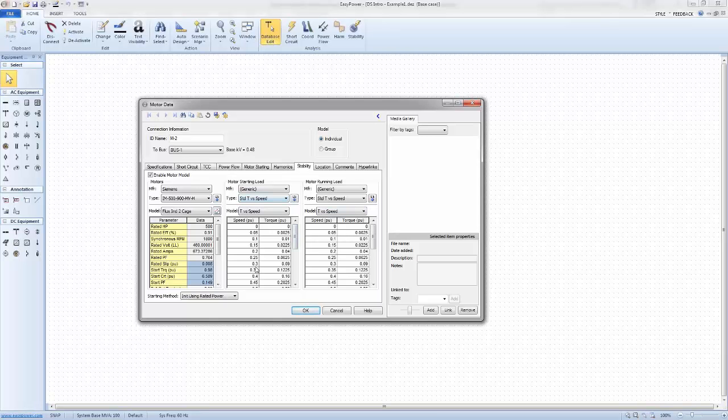And these models and curves are torque versus speed, or torque versus slip. Those of you who have more knowledge about induction machines know that torque versus slip is one of the very first types of data or curves that you would receive when you buy or start using an induction motor in your project.